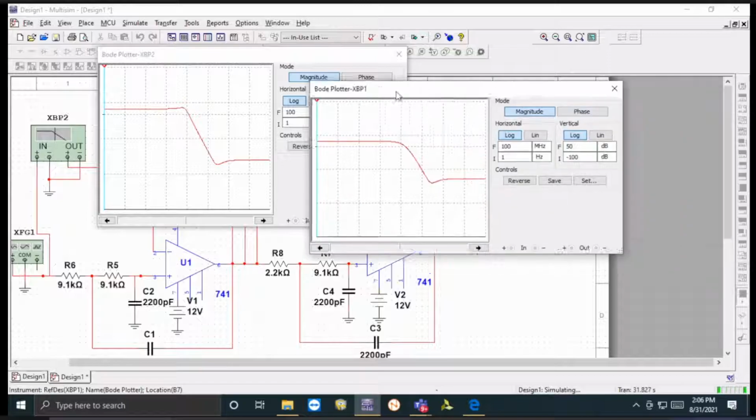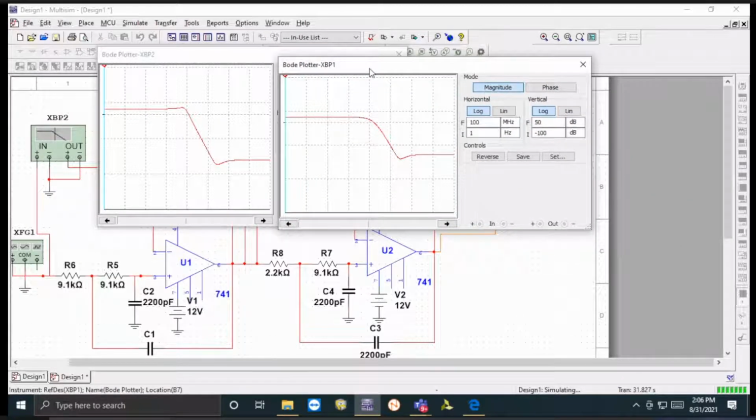So we can compare these two very easily, you can see, right? So we can see the smoothness. Definitely the property of the Butterworth filter will be maintained, you can see it has this type of behavior. But you can observe the smoothness. Why? Because this is the output for the second one, then we have the fourth order low pass Butterworth filter, and so we have smooth curves here and here both, right?